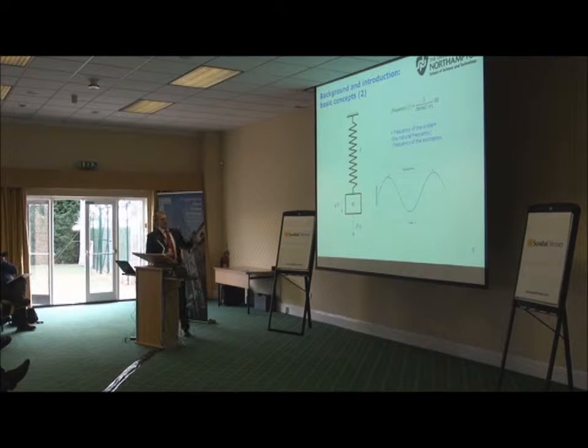When we have a vibrating system, and here's a very simple spring and mass arrangement, when we disturb the mass, it will move periodically. And typically, we'll see this kind of motion will repeat itself over time. And this repetition time we call periodic time. The periodic time can be linked to the frequency. And this is where the real issue is, the frequency issue. In some ranges of frequencies, we have the issue of ride quality. In another range, we might not feel vibration. However, it still can affect the structural integrity of the system.